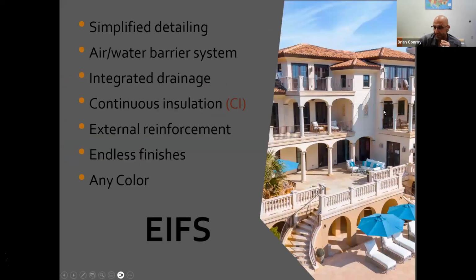So: simplified detailing, air and water barrier, integrated drainage, continuous insulation, reinforcing mesh, endless finishes, endless color. That is what EIFS is.